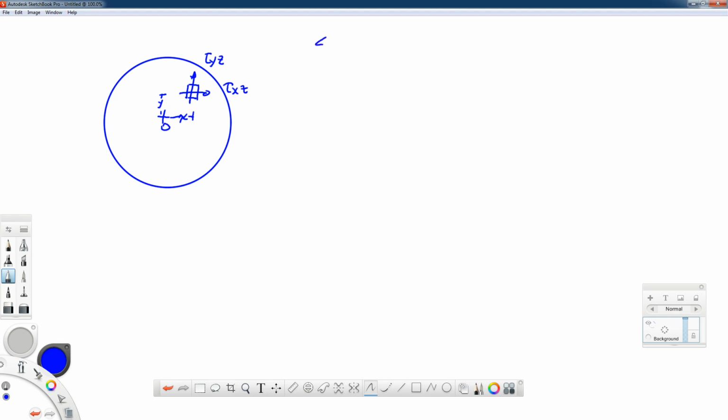If we want to do the summation of torques, we can take that way as positive. We're going to have to integrate over the area the positive contributions, the tau yz times the x distance, and counteracting that is the tau xz times the y distance. We have to integrate that over the area, so we have units of torque, and that would be equal to the resultant torque.